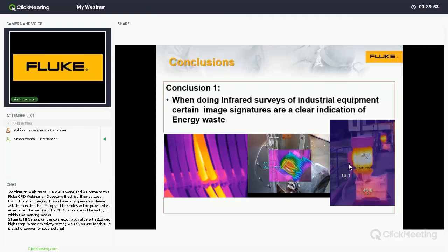And this is caused by harmonics creating extra heat, which reduces insulation life, unbalance or overload, both mechanical and electrical overload. So using thermography, it is very easy to not only find certain faults, but to identify where we've got energy waste.